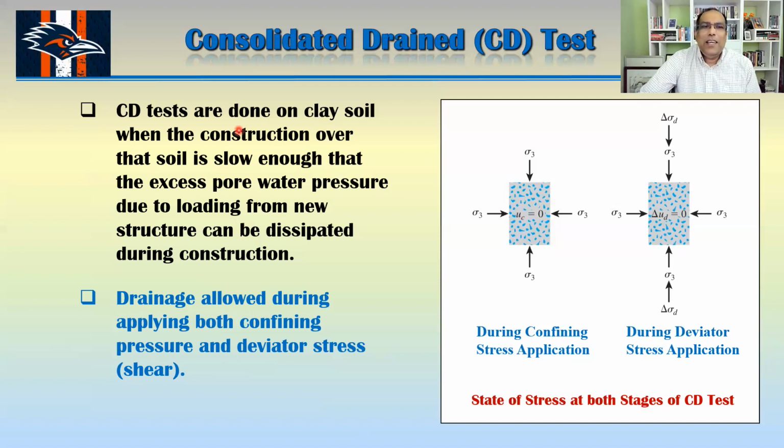So your consolidated drained test will provide you the drained strength, which is actually the highest strength for any clay soil.